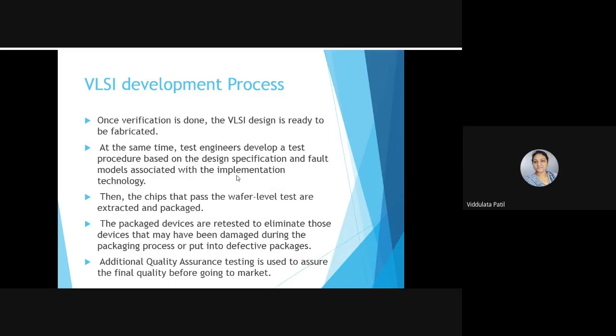After that, this VLSI design is ready to fabricate. Once physical verification is done, we go for the VLSI design, and at the same time, the test engineers develop a test procedure that is based on design specification and fault models associated with that implementation technology. So here the task of the test engineer starts. The work for the test engineer starts from this step, that they now need to develop a certain procedure.